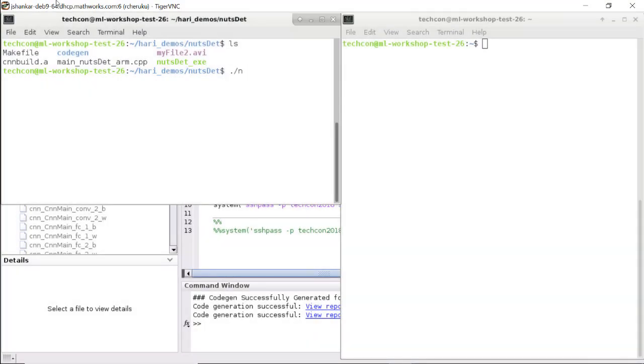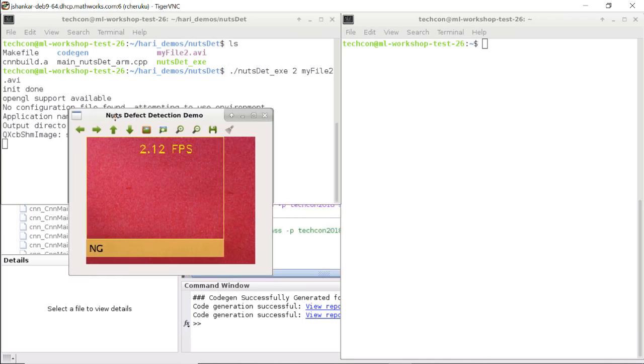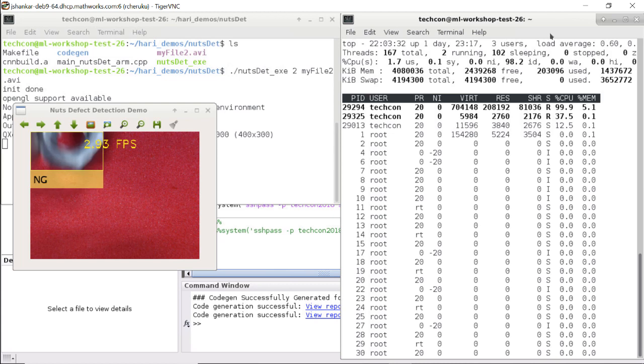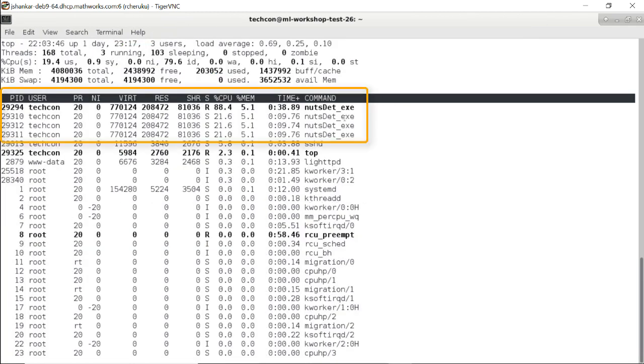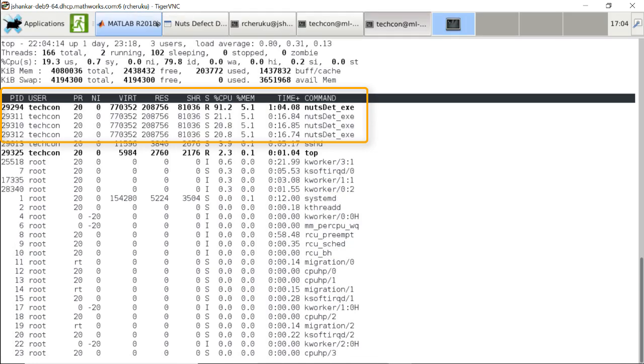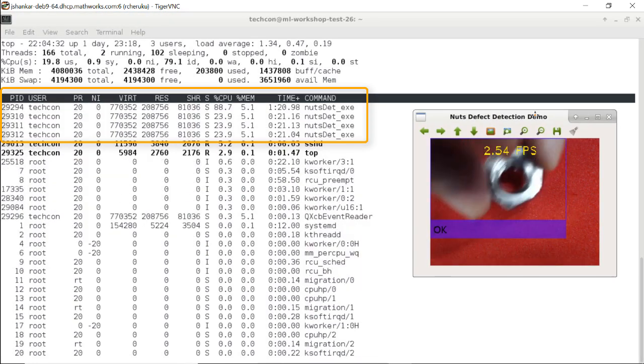This example application has relatively low frame rate requirements, and so such applications can be deployed on Cortex A platforms or even Cortex M platforms. Furthermore, the application is also using multiple CPU cores on the HiKey board through Arm Compute, since the Arm Compute library was built with OpenMP. And the generated code using Arm Compute leverages the available cores accordingly on your target hardware, as you can see here.